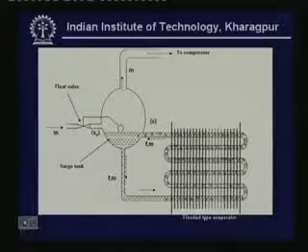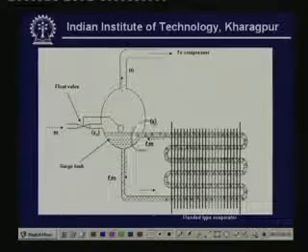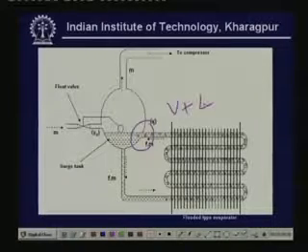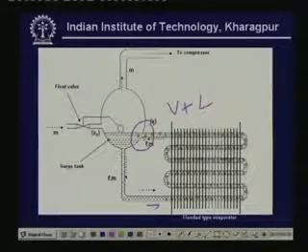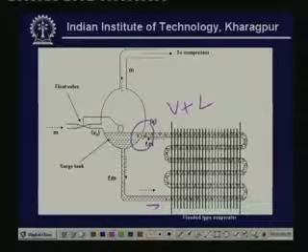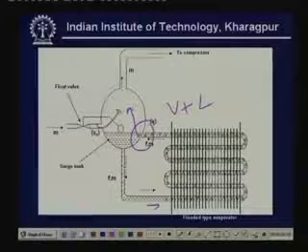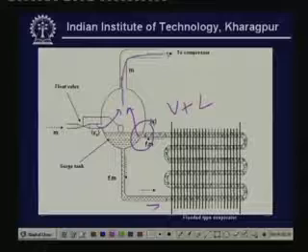So, you find that at the outlet of the evaporator again you have a vapor-liquid mixture. This is the feature of a flooded type of evaporator. Not all that refrigerant that goes to the evaporator will evaporate. Okay. There will be a large amount which is unevaporated. The unevaporated amount will simply recirculate. So, whatever vapor is there, plus whatever vapor is generated here, both will be compressed by the compressor. Okay. So, this is the flooded type evaporator.